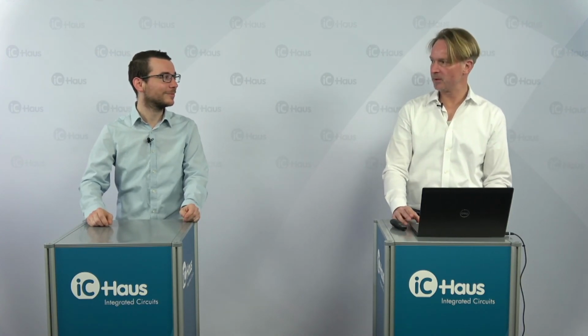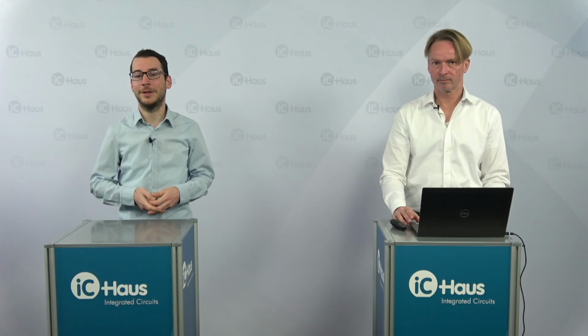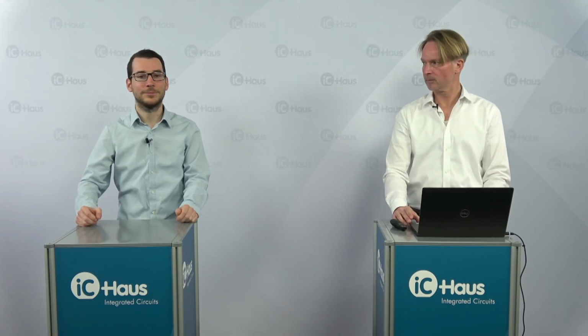The next question is: is it possible to connect more than one slave to the BiSS master? Yes, so it is possible to connect several BiSS Line slaves to one BiSS Line master using the BiSS Line protocol. For your application using iC-BL, I would recommend to get in touch directly, since our software is not yet ready to provide a setup with several BiSS Line slaves connected to one BiSS Line master. Excellent, thank you. We carry on with the next question.